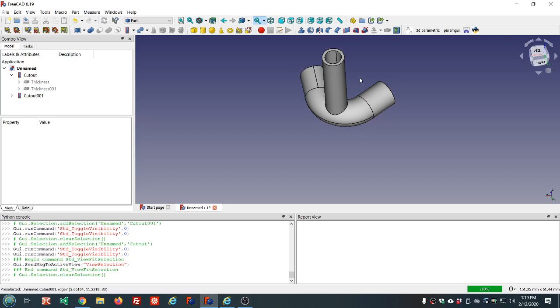It's not really something, honestly, that I've used very much. I prefer that first method I showed, where we just make it all solid, fuse it, and then use the thickness operation. With thickness, it can be contrary at times. The good thing about FreeCAD is almost always multiple ways to achieve the same thing, or something similar enough it makes no difference. So it's good to know all the different ways, so if one is not working for some reason, you can fall back to the other. It's good to know this constructed solid geometry approach, because you might find yourself in a situation where using a sketch-based approach is just not working. So you'll have this to fall back on and use it and get your project done.